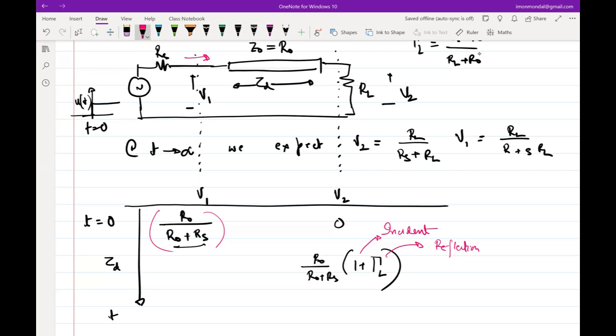One minus reflection coefficient at the front side times. We will say that, but when the signal just went through, there is no reflection, because in order to have a reflection, you need to have a delay. If there is no delay, the concept of signal traveling and returning back doesn't exist. If you want to impose reflection there, I presume the question that you are thinking is, why didn't I put the reflection coefficient concept for the forward going wave at V1?